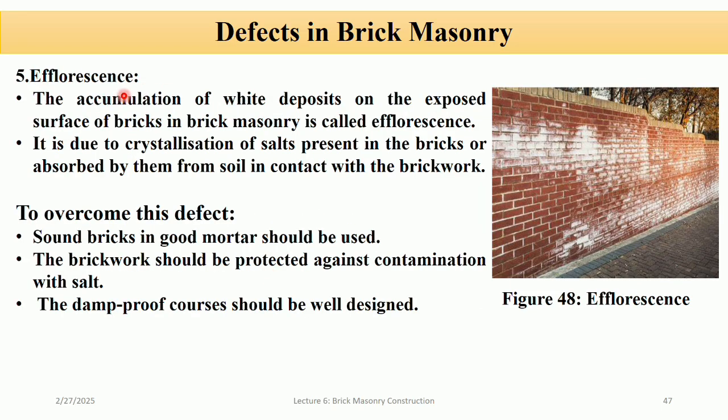Efflorescence. So efflorescence is the white powdery deposit of salt that appears on the surface of brick, mortar or concrete. So to overcome this defect, sound bricks and good mortar should be used.